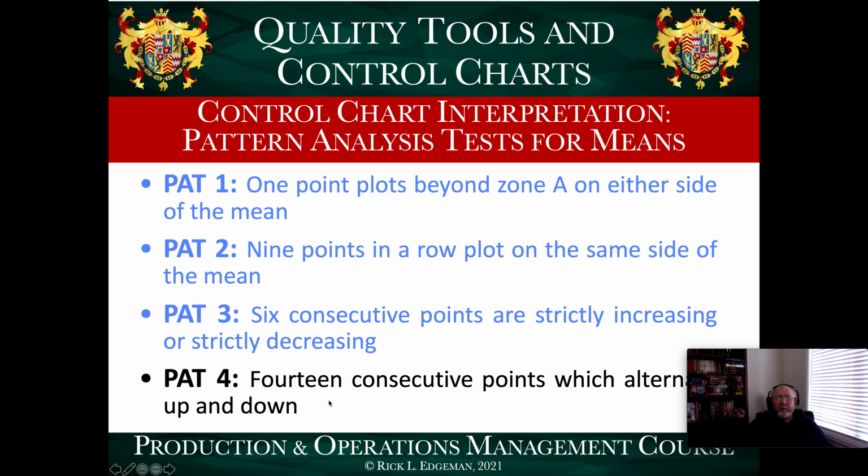Okay. The other typical explanation for this one is that you think you have a chart on one process, but in fact you have 2 different processes. So, you're using 2 machines to produce the same thing, and you think they're performing similarly, but they're not. So sample 1 is from machine A, sample 2 from machine B. A, B, A, B, A, B. Or first shift, second shift, first shift, second shift, first shift, second shift. Person 1, person 2, person 1, person 2. Things like that. The solution there is, as much as you may want those to be identical, they're not.